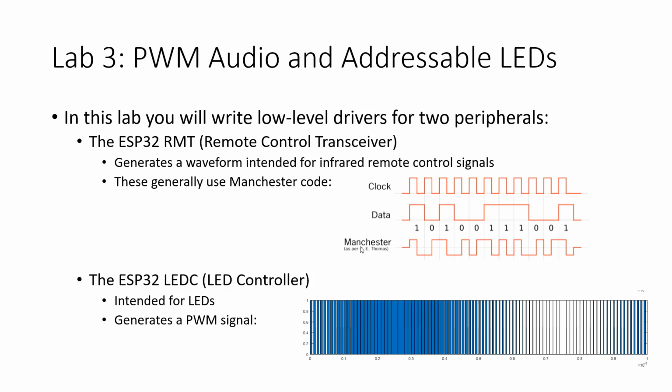So basically, for an infrared control, you modulate the Manchester encoded signal on top of a carrier signal, which is something we don't have to worry about, but is supported in the RMT. We just turn that feature off, right? Like how radio waves work. Yeah, exactly. It's similar to that, except that it's not a sinusoid. The carrier wave is not a sinusoid. It's a square wave.